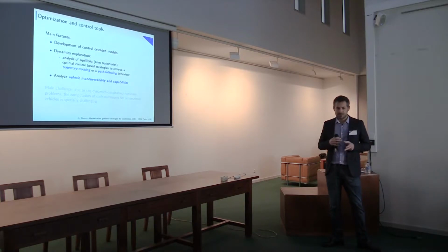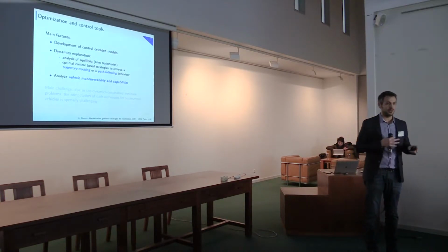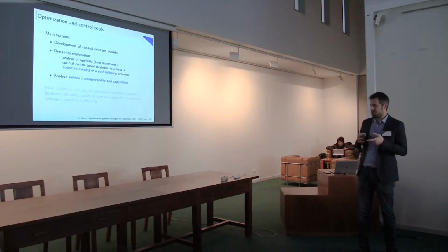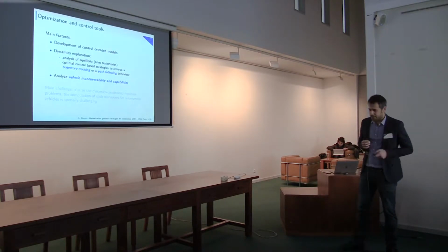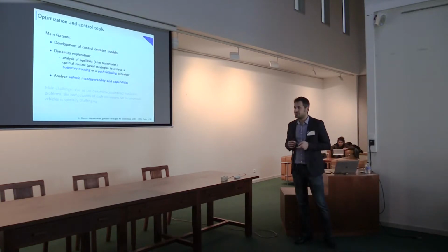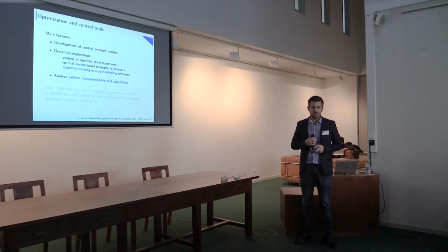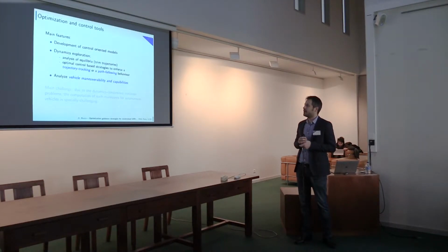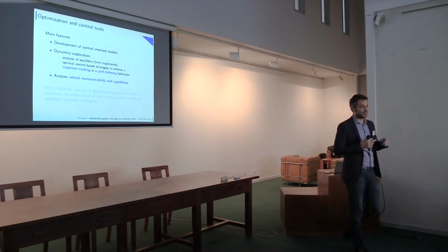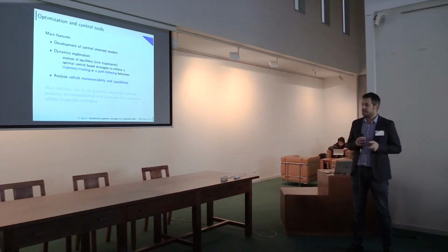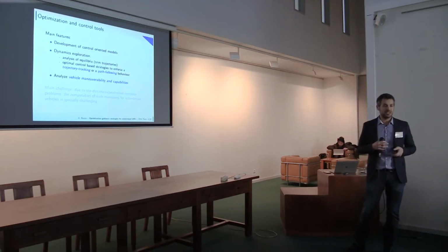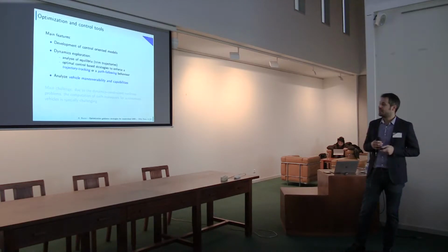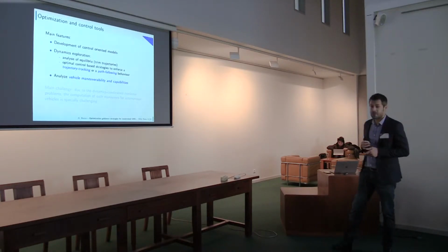Then, given a model, you start thinking about what kind of trajectory we can do. For a UAV, it's like an analysis of equilibrium, so you are studying the trim trajectories. And then you apply some optimal control-based strategies in order to explore the system. What we have proposed is called a virtual target approach, in order to enforce a trajectory tracking or path following behavior. And given the trajectory of our system, we can analyze vehicle maneuverability and capabilities.